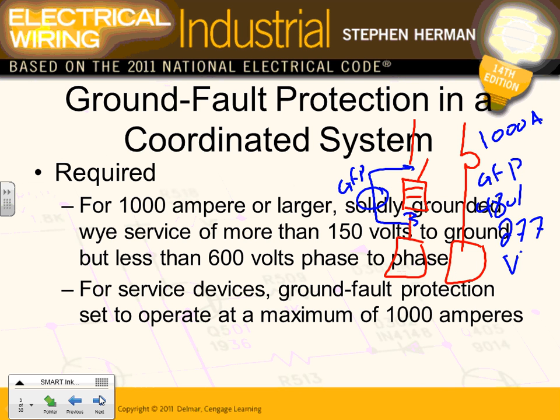So the smarter people, a long time ago, discovered that you need another protection called ground fault protection. It looks at the current in each of the three phases and in the neutral, calculates them, and if the difference is substantial, this means you have a ground fault somewhere in the system. It alarms and or trips.